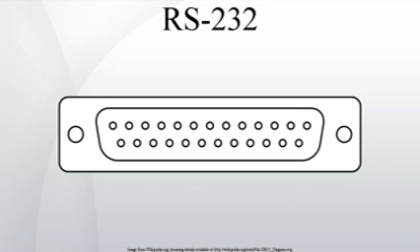This was eventually codified in version RS-232E, actually TIA-232E by that time, by defining a new signal, RTR, ready to receive, which is CCITT V.24 circuit 133. TIA-232E and the corresponding international standards were updated to show that circuit 133, when implemented, shares the same pin as RTS, request to send, and that when 133 is in use, RTS is assumed by the DCE to be on at all times.